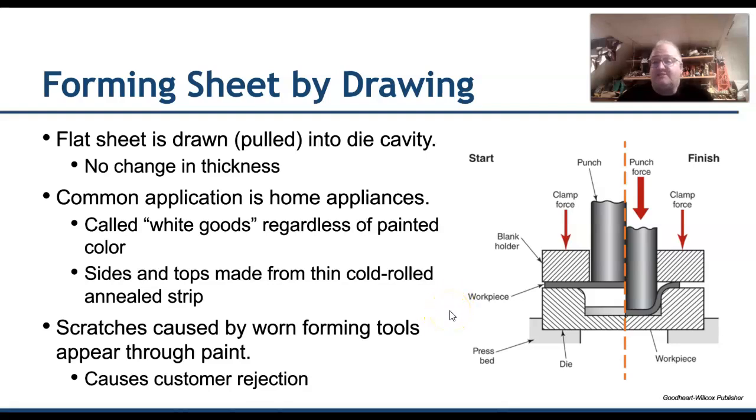As we have these forming tools, it's important to understand any defect or any variation, even something as small as a change in surface material or surface finishes, can cause nicks or cause problems as we draw that sheet metal over there. We can also get the material on the sheet to pick up on the tooling through friction, and that is also going to cause some problems as we are drawing and forming sheet in this way.